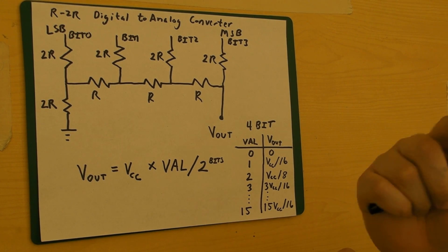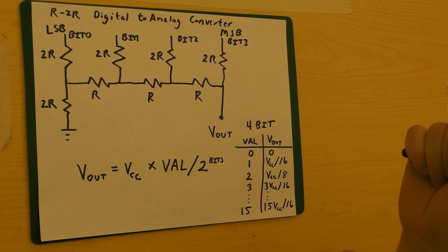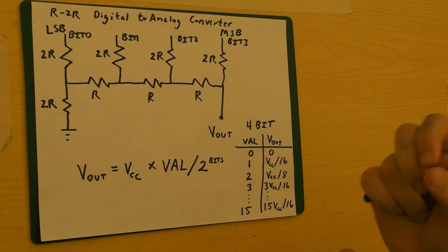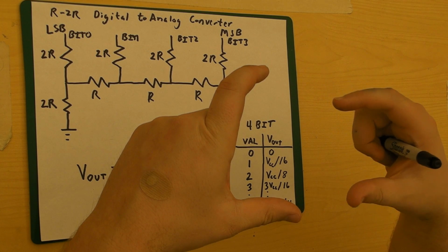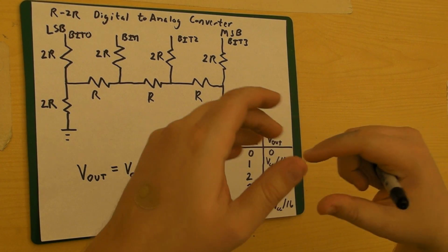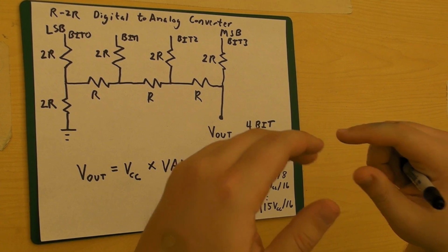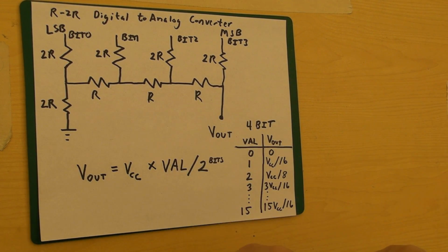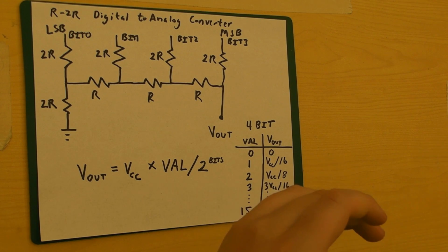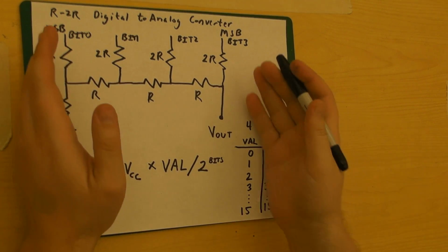So your CD is spinning around. It has the bits for your songs all on the CD. Your microcontroller, the microcontroller in your CD player, reads that. And once it reads the values, it's then got to change those digital values to analog. How it does that, it has a line for each of the 16 bits for the music. It then combines those bits into one of 65,000 plus values, and those values then go to your headset. And how that works is something like this.